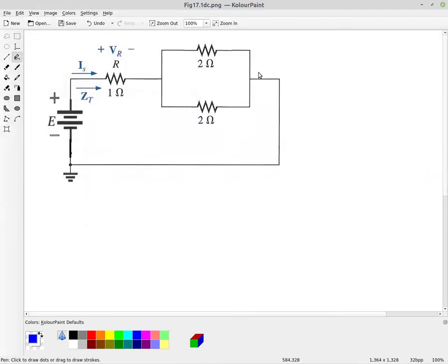This video is going to consider series parallel circuits for AC circuits, but we're going to start off here with a DC circuit to just kind of remember some of the fundamentals. So we know for a DC circuit, which is actually also true for AC, that resistances in series simply add up. So you just take one resistor plus the next one in series plus the next one in series, and so those resistances all add up.